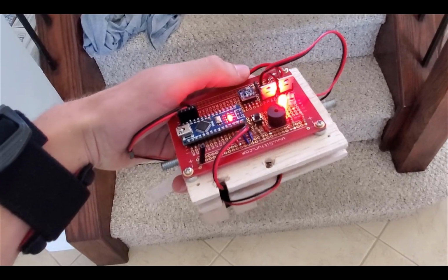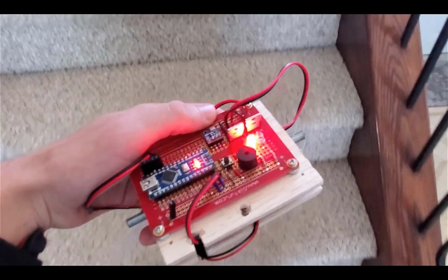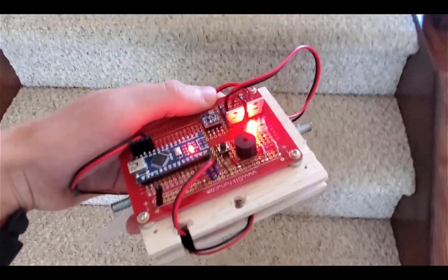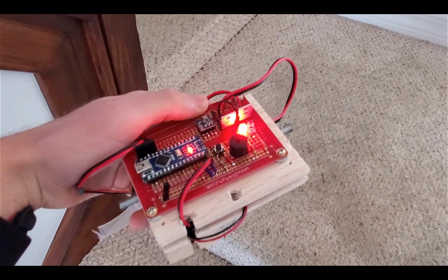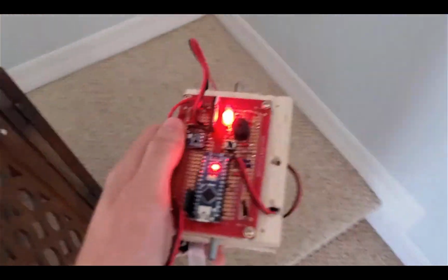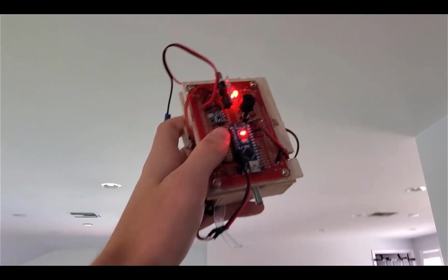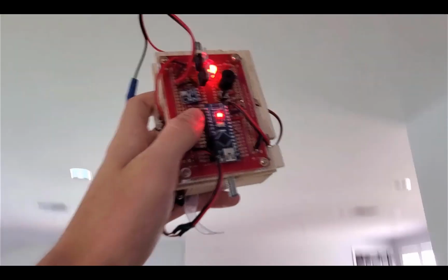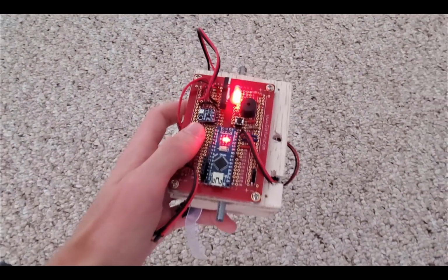Now it's waiting to take off, and when it gets above a certain altitude, that means that it's detected that it's taken off, and we know that it is detected takeoff when the beeper stops beeping. And so I'll go the rest of the way upstairs, and we're just simulating the rocket going up right now. Now when the rocket gets to the top of its flight and it starts going down, we're going to detect that, and that beep means that the MOSFET is firing right now.